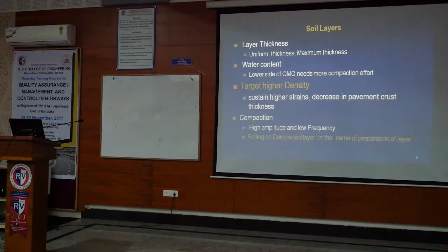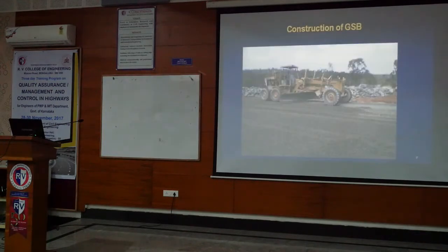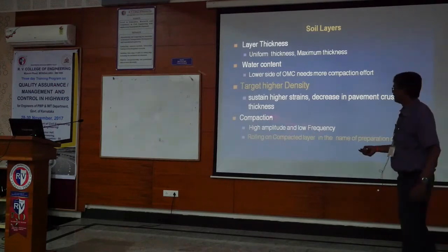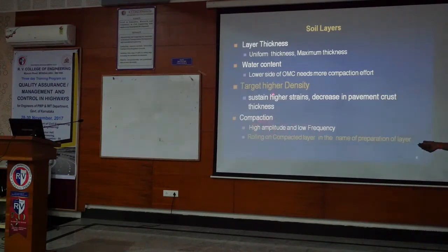And then, whenever we are compacting the soil layers, to get this high density we need to target a high amplitude compactor and low thickness, vice versa for the bituminous layers.